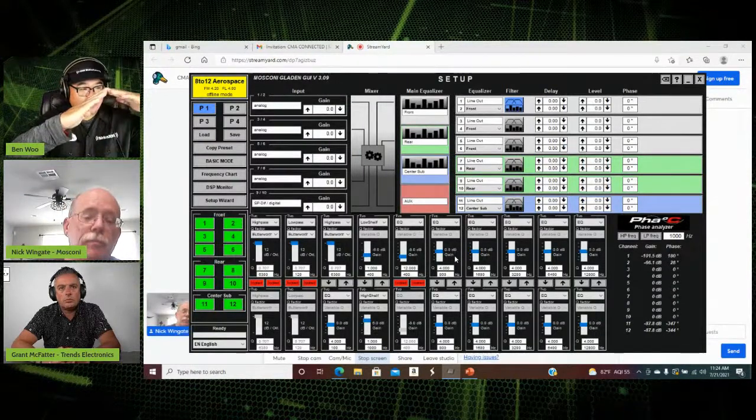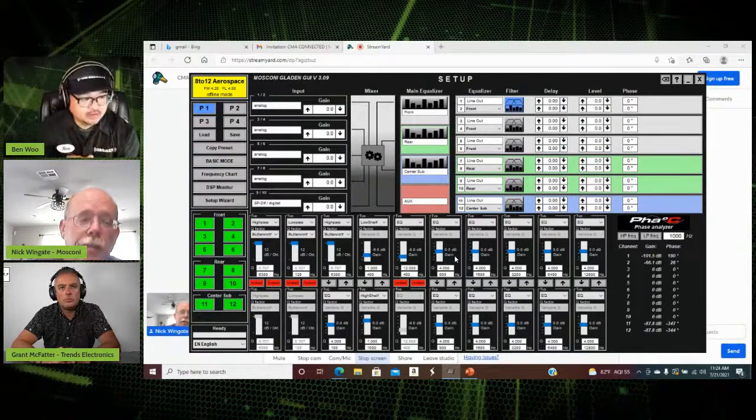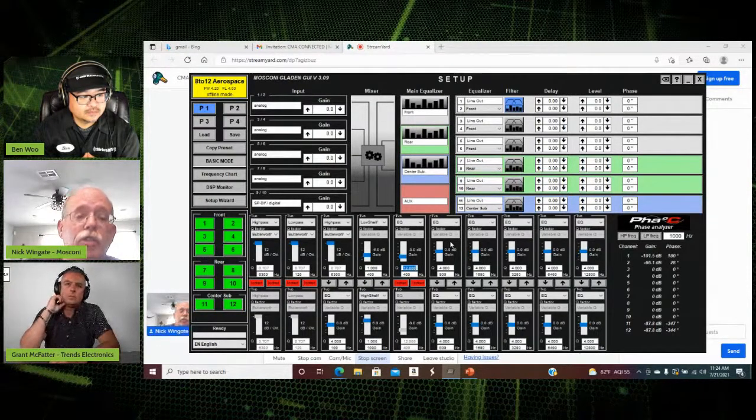So as you double, basically this is what happens, right? As far as the impact outside of that frequency. That's correct. It will start narrowing it. And so you've got these additional 5 to play with. And in a mid-bass driver, when we're affecting 80 hertz to probably 300 hertz, this is extremely powerful.